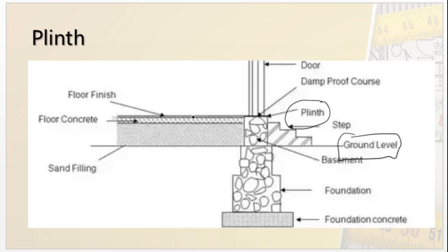To protect the building from that, based on the survey, the flood level and the guidelines, we generally define this plinth level for the building. Then we start the floors over this plinth. So this is the plinth level, as you can see.